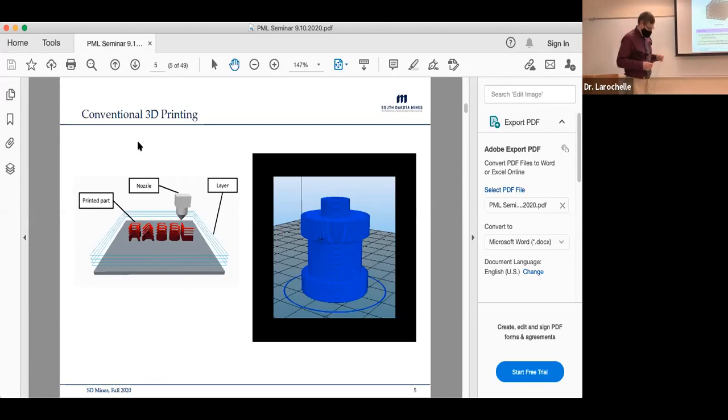So from a kinematics perspective and also from an additive manufacturing perspective, that's very limited, right? When you can only do 2.5D printing and you've got to print in these parallel planes. So what we wanted to look at was, can we use something that both of us were very familiar with, which is traditional industrial robot arms that have 6 degrees of freedom and can arbitrarily position something in the 6-dimensional world we live in.